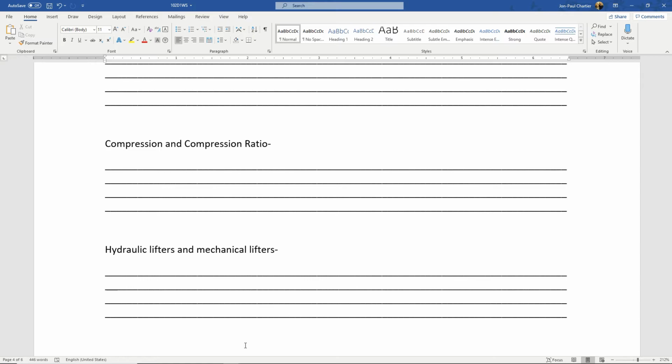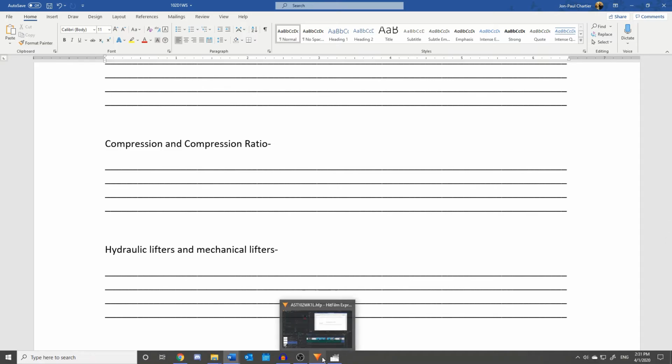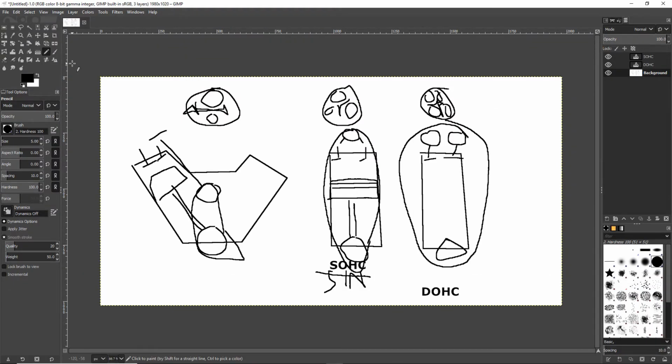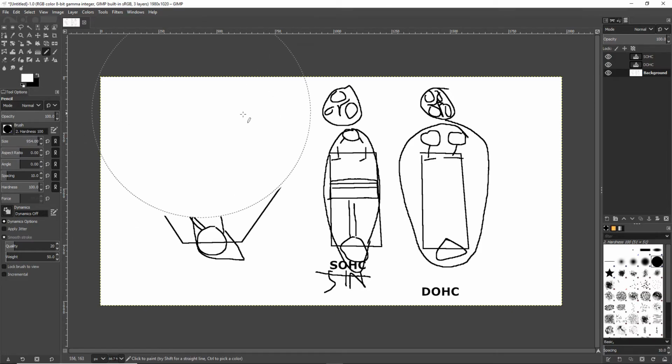Say it's my dad's 86 Monte Carlo, if they even made those in 86, I don't know. And it's got 400,000 miles on it, and it's running rough. We're going to start with air, fuel, and spark, but we find all those are good. Hey man, why don't we run a compression test? Oh, look, it has low compression. So actually the Miata in my driveway, one of its big problems is I did a compression test on it, and let's go back to my drawing here. When you do a compression test, you're going to do all the cylinders one at a time to try to figure out which one it is, or perhaps there's more than one of them that are having problems, right?